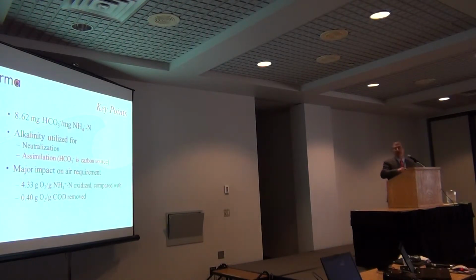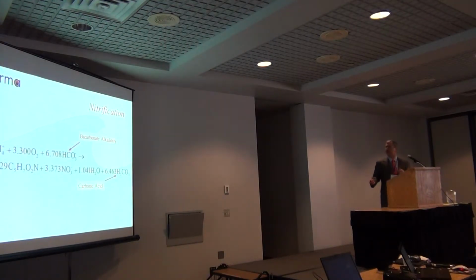Now, one of the things I'm going to highlight later on is you can get some of this back if you can effectively denitrify. Because if you think of oxygen as a chemical, some of the bacteria can use either oxygen or nitrate to breathe, which means the nitrate has some value for respiration. And if you get as much denitrification out of that as possible, you can recover some of the energy that you've put in to converting the ammonia. I'll talk about that more later.